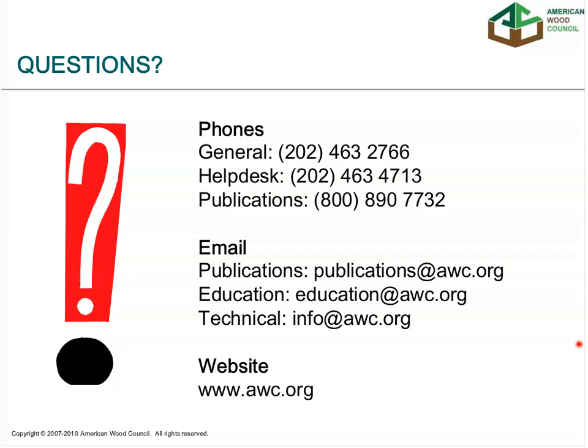The dirty little secret about LRFD in this particular version of the NDS, and I think we talked about this earlier, is that the phis actually cancel out in the design process. So I'm hoping the phi canceled out in that example problem. I'll go back and look at that and make sure. But that's the intent. That is being fixed also in the 2011 version of the NDS, which is coming out fourth quarter of 2011. And again, there is an FAQ on our website that talks about the reason for that. But again, that'll be clarified in the next version.